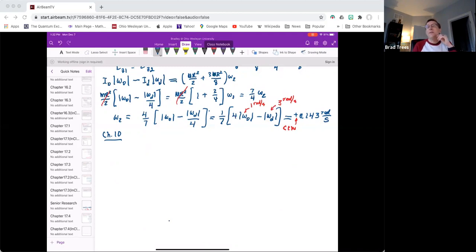And what we talked about there was when you have a rigid body that can rotate about a fixed axis, the way you get it to rotate is you apply a force somewhere. And if that force has what's called a moment arm, you will get what's called a torque. And it's the torque that causes the object to rotate. So we need to be really clear on how to calculate torque.